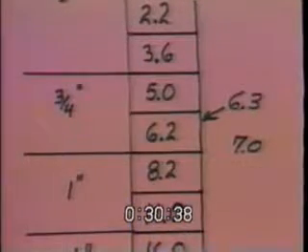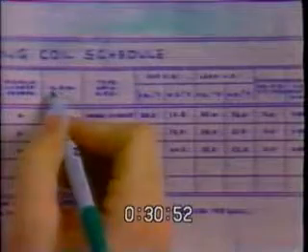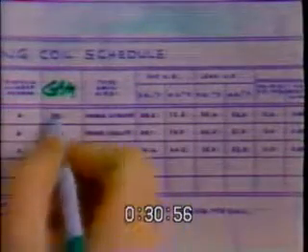A rule of thumb, go to the closer. Let's go ahead and work out a CV problem. Using that problem that we showed for the pressure drop, let's work out the CV for that same problem. Here we have the gallons per minute for a particular coil, in this case a cooling coil, and you can see that it's 291 gallons per minute.